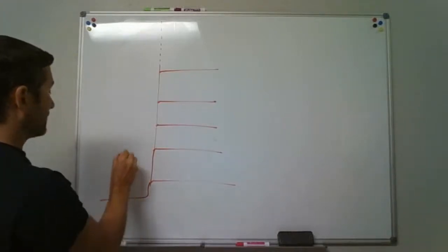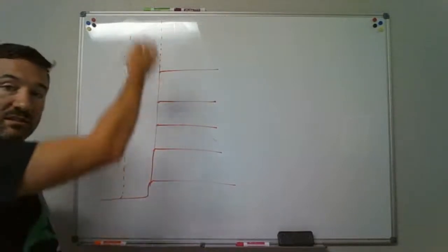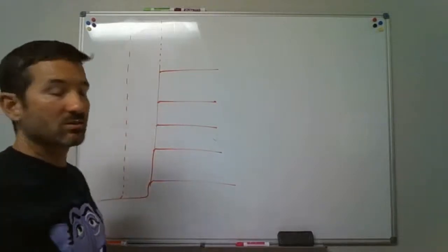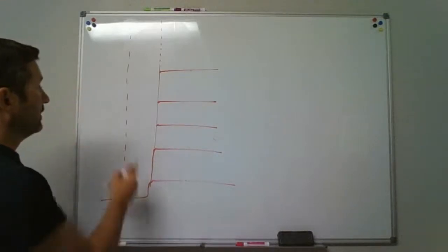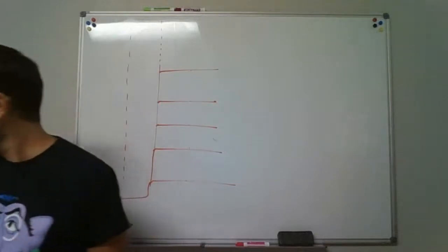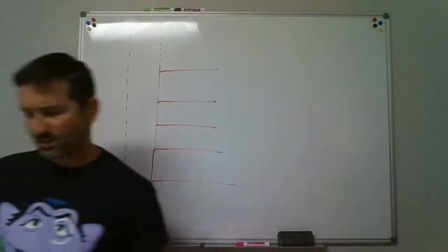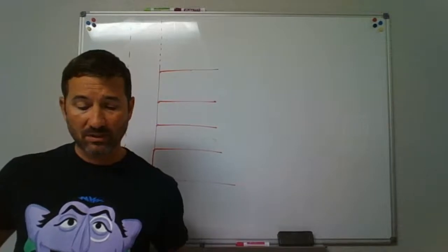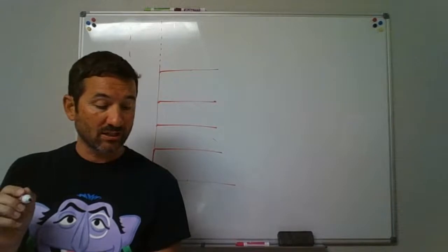Here's one possible location. We'll talk about the different locations of it. It's going to be a vent that's a stack itself, and vents can tie back over to that. So if you have 5 branch intervals or more, the building is going to require a vent stack. Okay. Let's see. Vent termination. Vent stacks or stack vents shall terminate outdoors to the open air or to a stack type air admittance valve in accordance with 918.